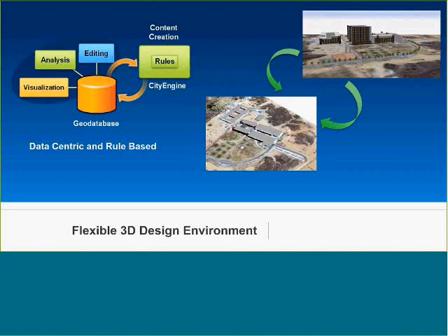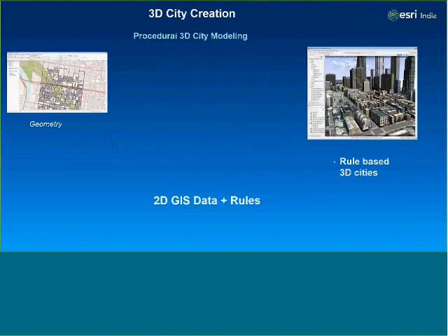As you could see in this particular example, you have a 2D footprint, which can be used and modeled across as a 3D data model. What it uses is, you have geometry. This can be your simple Esri shapefiles or file geodatabase. You have attributes such as what is the type of building, what is the zone, and what are the other parameters set up, like is it a residential apartment, is it a commercial apartment, what should be the building height, what are the setback parameters provided,